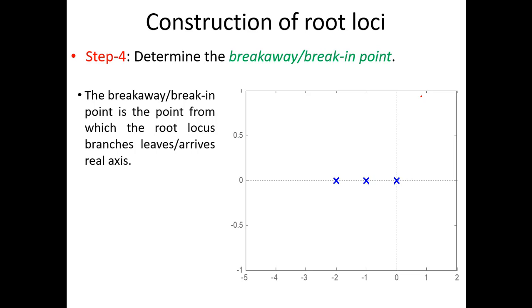Now let's talk about another quantity that is known as the breakaway or the break-in point. If the roots are coming from higher regions, we want to see that these roots are going in this direction. Now we want to see where it will land, where it will come back on this real axis, or if it will come or not, whether it is going in this direction or coming downward. We want to see at which point this root will fall in on the real axis. That is basically a break-in point, or if here it is going out, this will be known as the breakaway point.